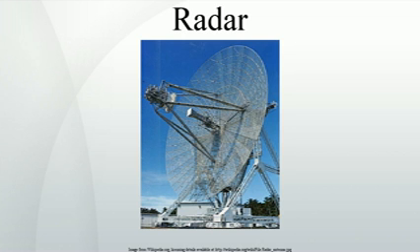There are 4 common track algorithms. Nearest neighbor, probabilistic data association, multiple hypothesis tracking, interactive multiple model, IMM. Radar video returns from aircraft can be subjected to a plot extraction process whereby spurious and interfering signals are discarded. A sequence of target returns can be monitored through a device known as a plot extractor. The non-relevant real-time returns can be removed from the displayed information and a single plot displayed.